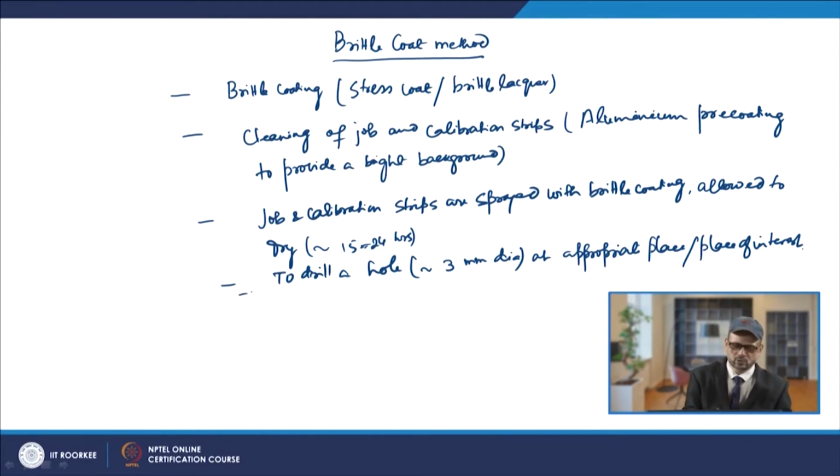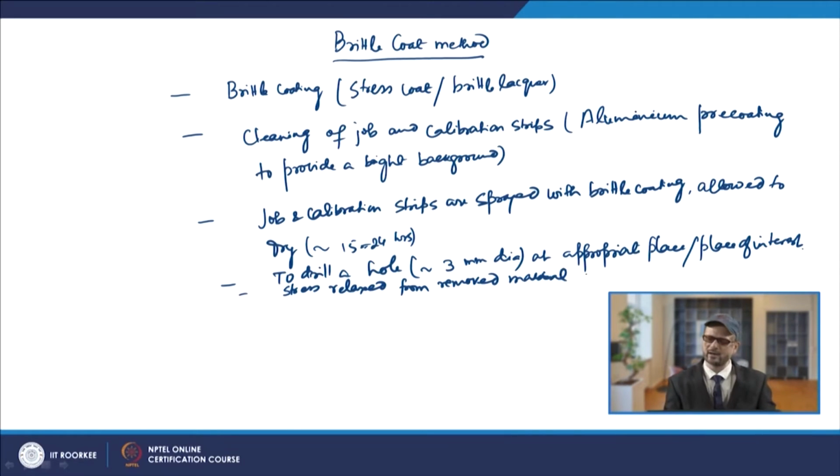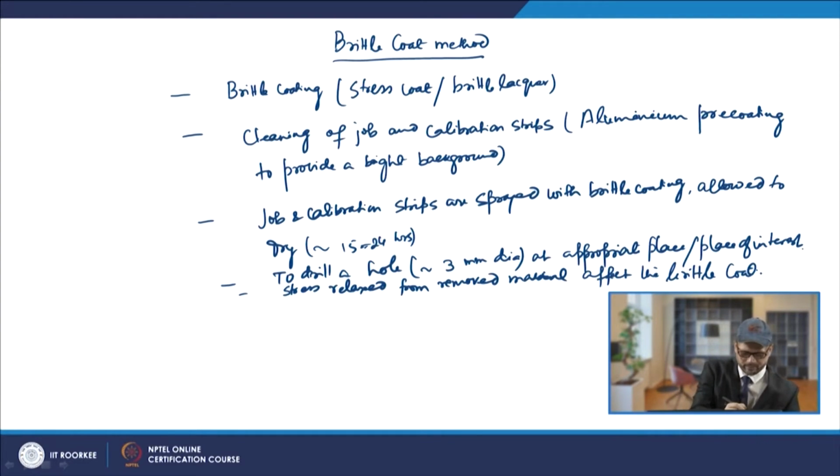So, you will have cracks on the surface in that brittle coat. The stress relaxed from the removed material will affect the brittle coat. So, you will have the presence of a crack pattern which will be observed, and the job will basically be stressed with biaxial tensile stresses.